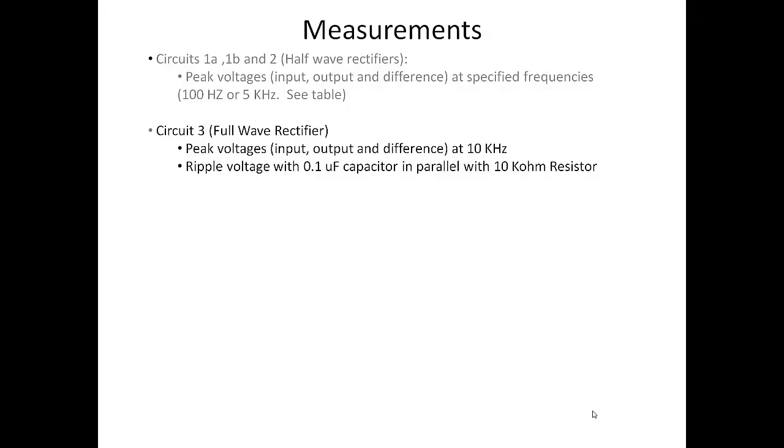Before the DC voltage is regulated, the ripple in the rectifier must be reduced by placing a capacitor in parallel with the load resistor. In power supply designs, this capacitor is very large and is chosen to limit the ripple for the maximum amount of current that the supply can source.